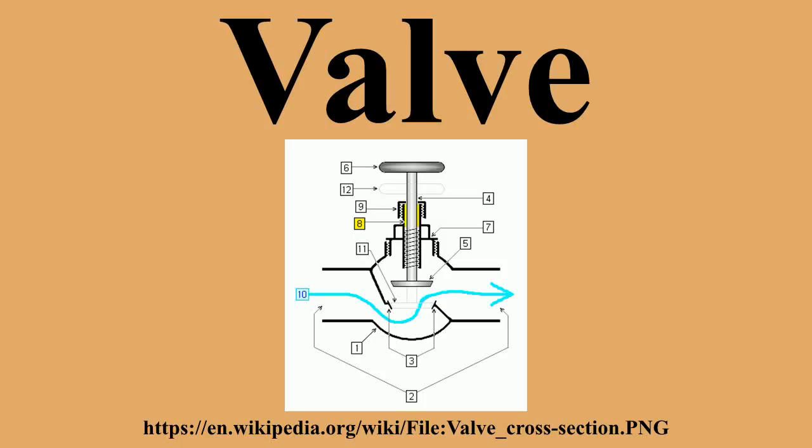Other examples of normally closed valves are emergency shutdown valves, which are kept open when the system is in operation and will automatically shut by taking away the power supply. This happens when there is a problem with a unit or a section of a fluid system, such as a leak, in order to isolate the problem from the rest of the system.